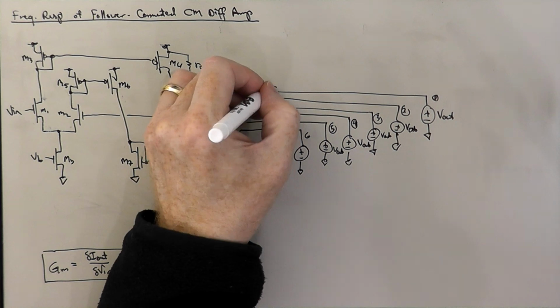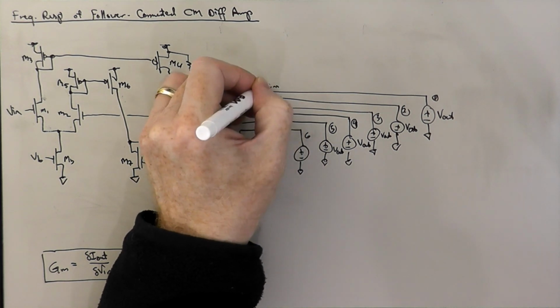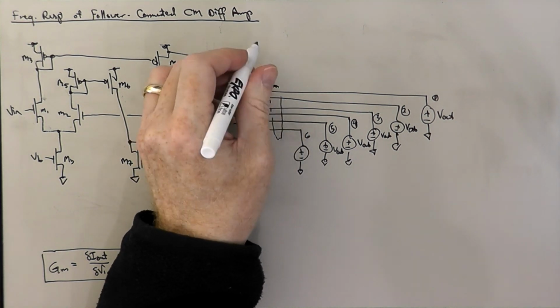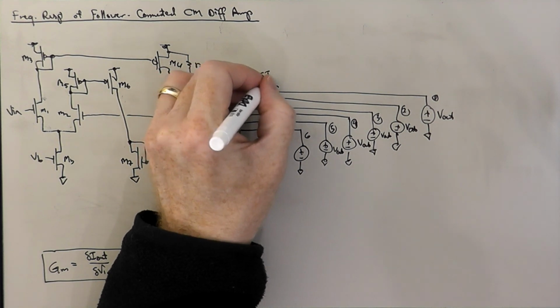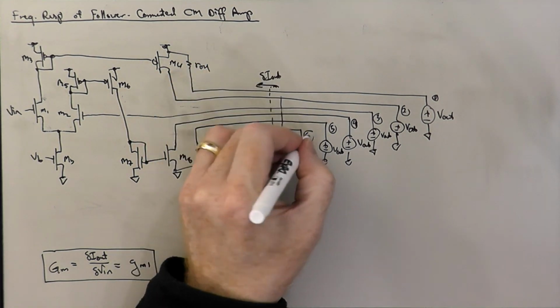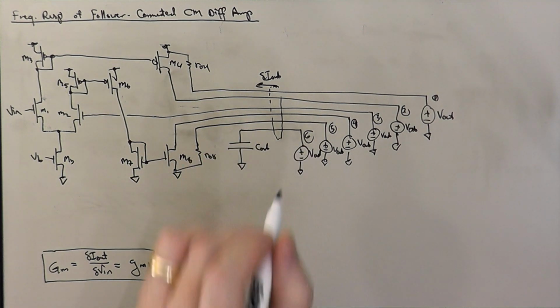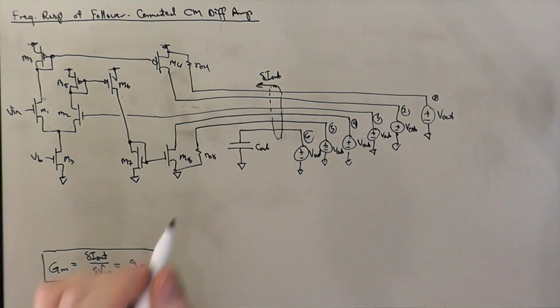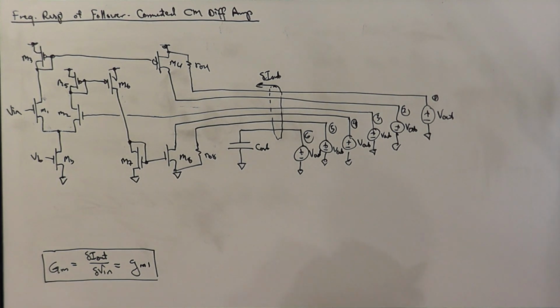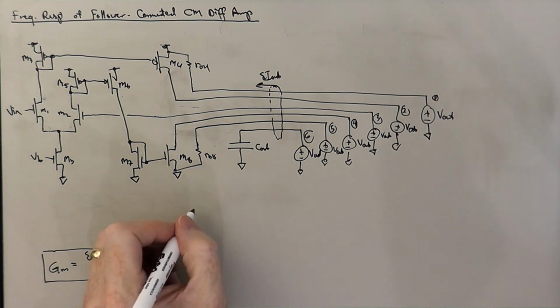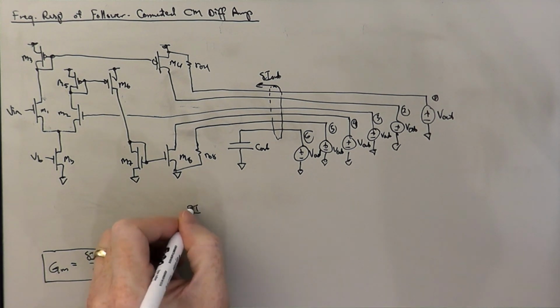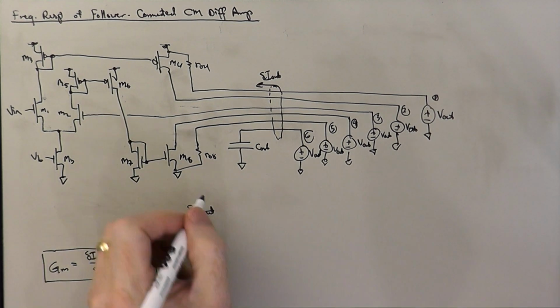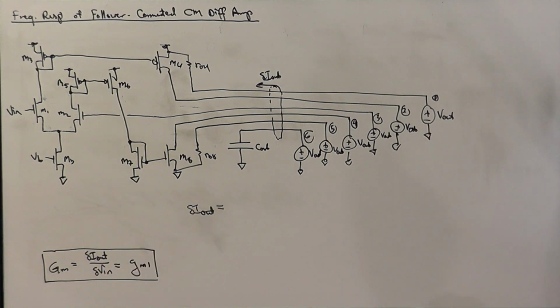And we're interested in the total amount of current flowing through this giant bundle of 6 wires. And so instead of applying all of our output sources simultaneously, we're going to apply them one at a time and accumulate our delta I out, and they combine by superposition.